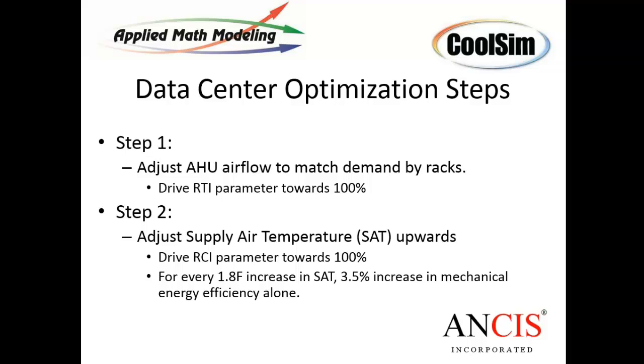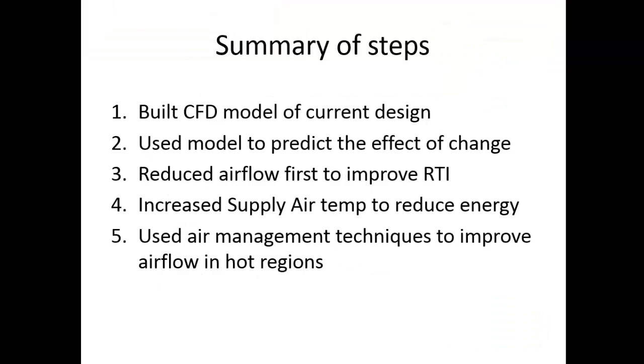As a rule of thumb, generally people say that for every degree F you get a percent increase in your mechanical efficiency. It's actually, as you can see, a little better than that, depending on the situation. And as Magnus pointed out, if you've got any kind of economizer, whether it's air side or water side, if you can increase supply air temperature, the window of opportunity for using outside air to cool your data center, either directly or indirectly, goes up tremendously. And that reduces your energy by a significant amount. So raising supply air temp is important for a couple different reasons.